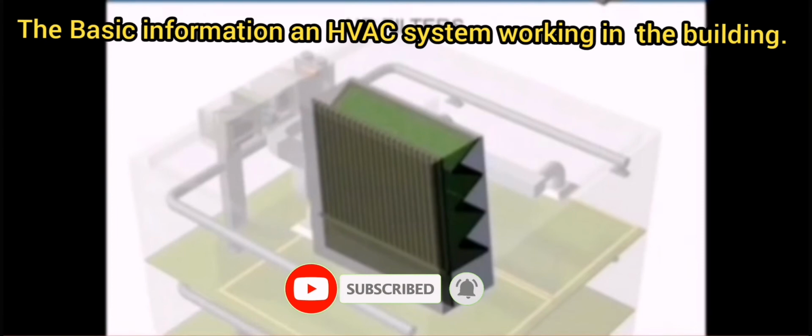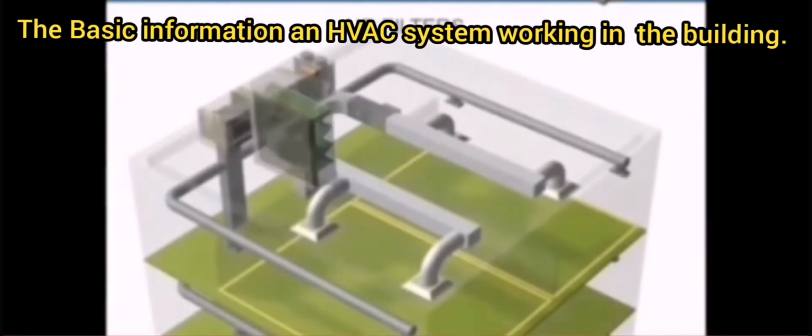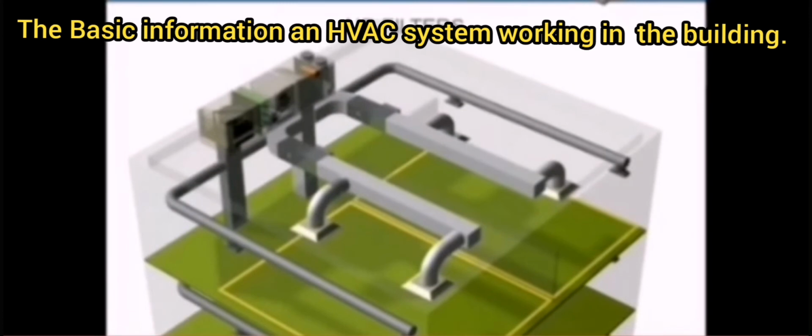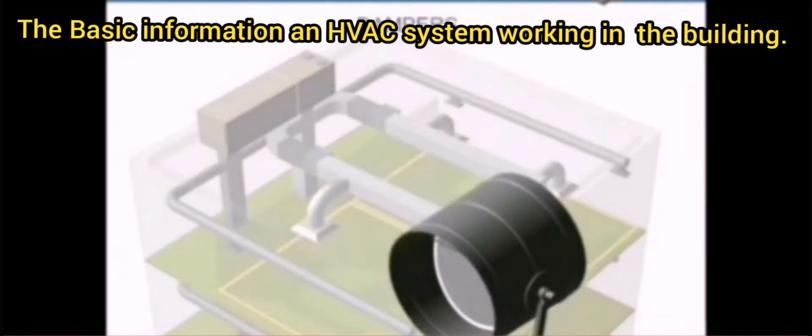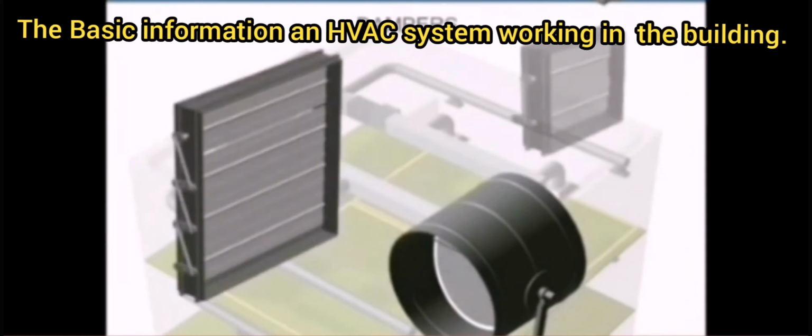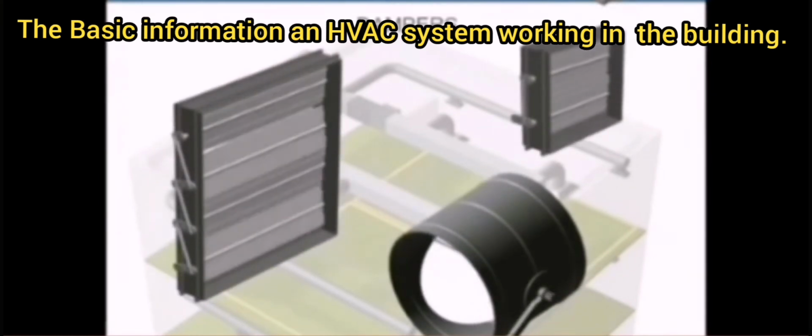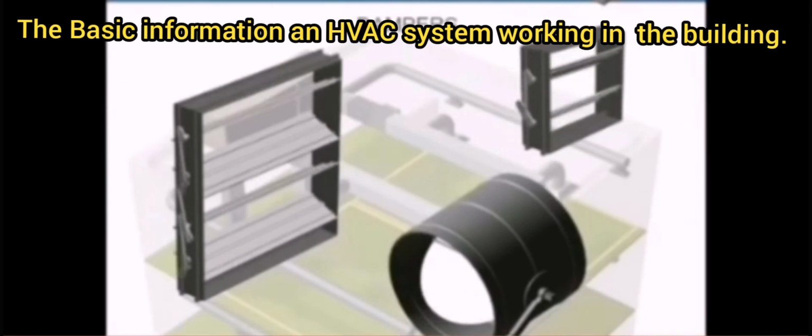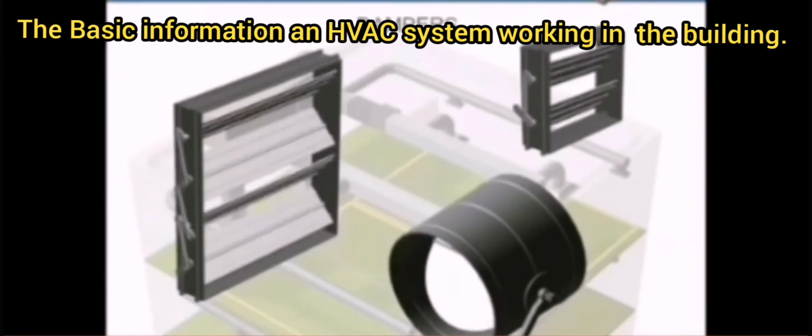General-purpose air filters will be included in the air handler itself, while more sophisticated filters, such as HEPA filters, may be used in the downstream ductwork. Ductwork. Round, square, and rectangular ductwork provides a path for the conditioned air from the air handling unit to the environment. A damper consists of one or more blades which can be used to control the amount of airflow through a duct. Manual dampers are used to ensure that different parts of the building receive proportional ventilation based on area and demand. Automated dampers may be installed at firewalls which close in the case of a fire.